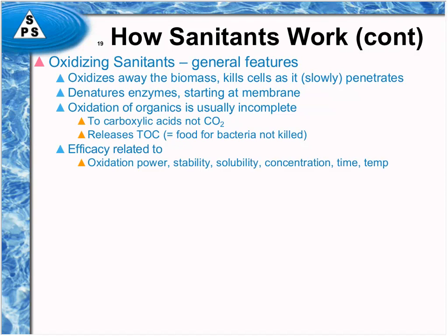The efficacy of any kind of oxidizing sanitizer is related to its oxidation power or oxidation potential, and its stability. Sometimes these oxidizing agents are naturally unstable and don't hang around for long. Ozone's a poster child for that. Then its solubility in water. Ozone, again, a poster child for poor solubility. The concentration that you're using, which is often limited by its solubility, and then the time and temperature of exposure.